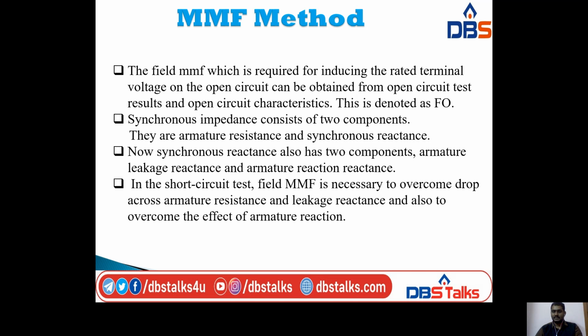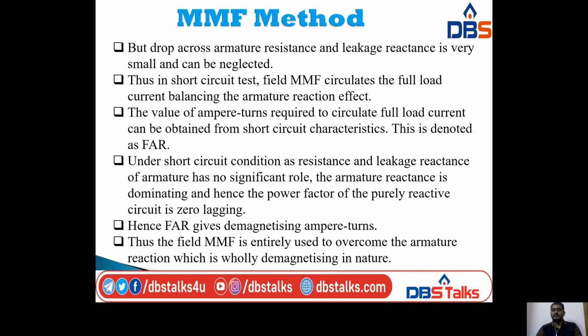In the short circuit test, field MMF is necessary to overcome the drop across armature resistance and leakage reactance, and also to overcome the effect of armature reaction. But the drop across armature resistance and leakage reactance is very small, that's why we are neglecting these drops. Thus, in the short circuit test, field MMF circulates the full load current, balancing the armature reaction effect.